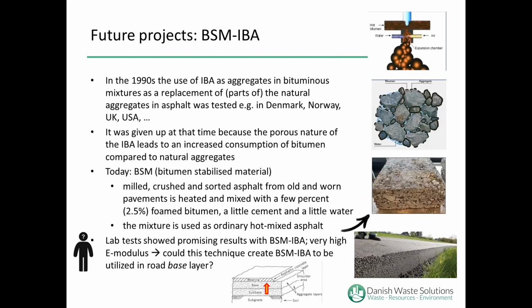Here is an example of some potential future applications of bottom ash. It's called bitumen stabilized material, BSM. The story is that already in the 90s, the use of bottom ash as aggregate in asphalt mixtures was investigated or tested in at least Denmark, Norway, the UK, and the USA. But back then it was given up because the porous nature of the bottom ash led to higher consumption of bitumen compared to natural aggregates. So the whole system was more expensive.